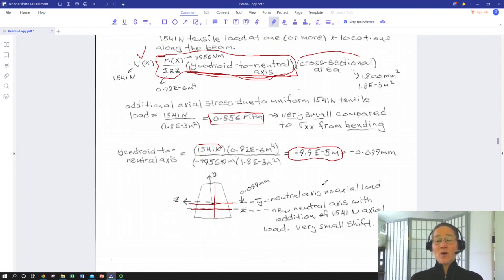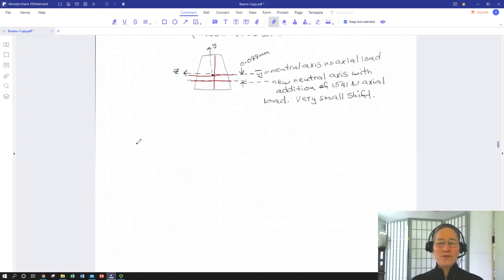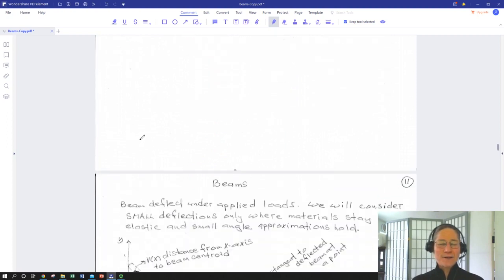So knowing where your neutral axis is and inferring where your max tensile axis is helps you space out your tensile reinforcement when you need to. And that's particularly important for concrete, because in that particular composite structure, you have your concrete matrix, which really can't support any tension. Polymers with fiber reinforcement tend to be a little more tolerant.